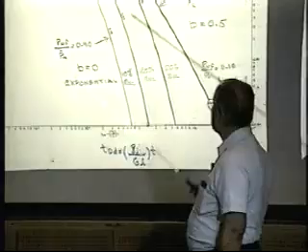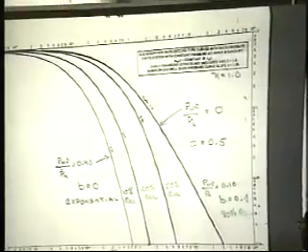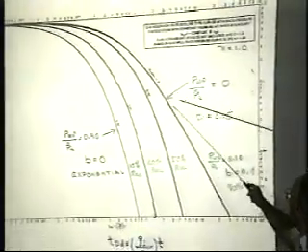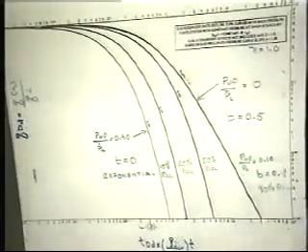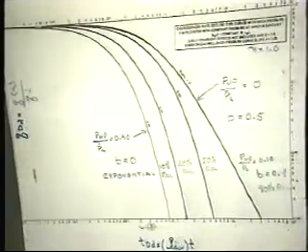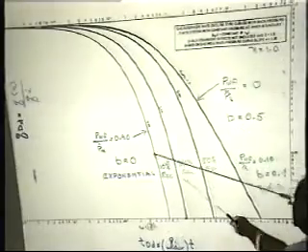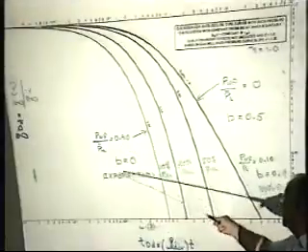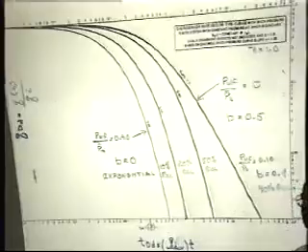I need to introduce here an example with a slope of 1 and different back pressures. Your PWF over 0 is a B of 0.5. It's exact from the equations. If you let the flowing pressure approach the shut-in pressure, like this limiting case here, where the flowing pressure to the shut-in pressure is 0.9, it's exponential. So the value of B is also a function of the back pressure.